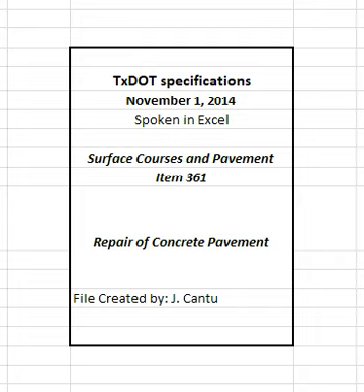Mix, place, and cure in accordance with the manufacturer's recommendation when material in DMS 4655, concrete repair materials, is used. Mix, place, and cure concrete in accordance with Item 360, concrete pavement when Class S, Class P, or Class E is used. Test Class S, Class P, and Class E concrete to the requirements of Section 360.4.2, Job Control Testing.